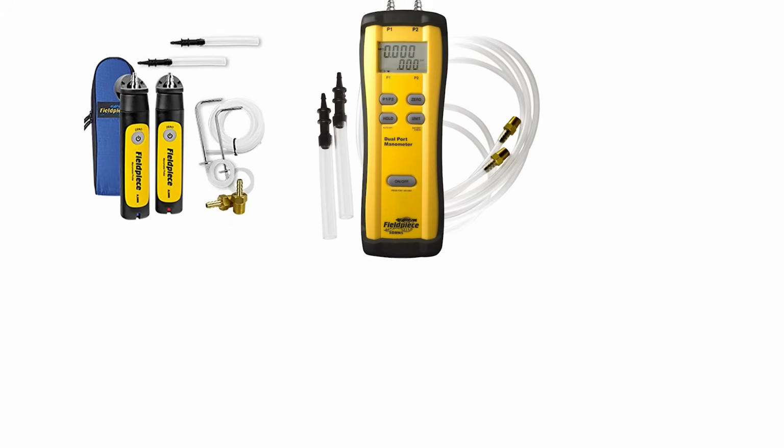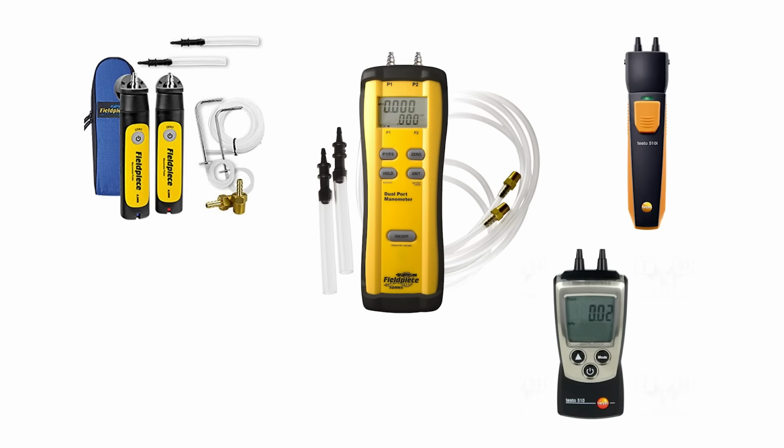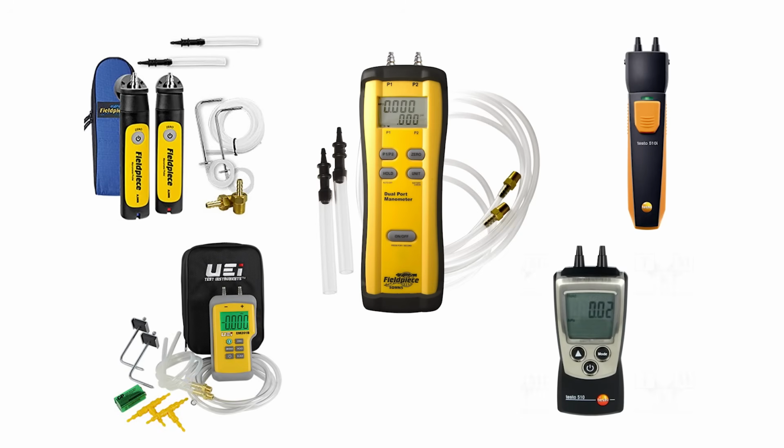The first one is what we call the utility manometer, or just your regular old service manometer. And that's like the field piece, whether it's a single port or a dual port. We'll talk a little bit about that. But it's the field piece and Testo and whatever other UEI, whatever other brands you have. And those are designed to measure in the inches of water column scale. Okay, so we'll start there.